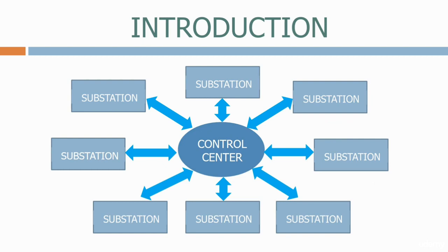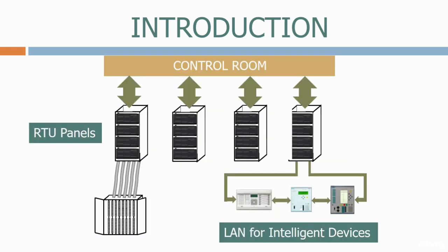SCADA systems are critical to the operation of most transmission substations, and they are used to provide control and monitoring functions. We will look at the typical architecture behind a SCADA system and see how we connect all the primary plant and other systems to the LANs and RTUs that interface with a SCADA system.